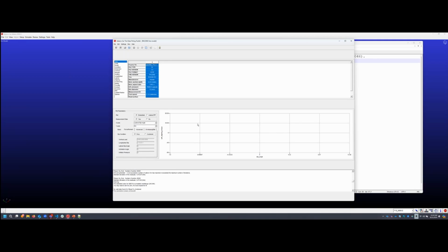For example, like Alex mentioned before, I was able to predict the toe and camber settings for the car within an error of 0.15 degrees for front and rear suspension. So I would say that's a pretty decent starting point, and it'll save you a lot of time during your testing phase when you're trying to adjust the actual car and get the best performance out of it. And that's pretty much it from my side, and I will leave it up to people for questions and anything else.